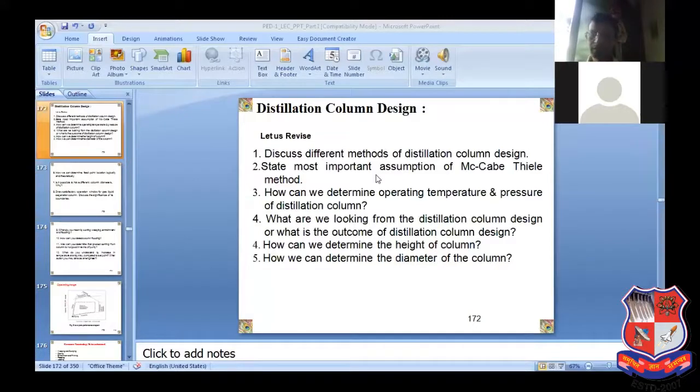If you remember, if you go through the assumptions given in the McCabe-Thiele method in a mass transfer operations book, then you can see that I can assume constant L1, L2, L3 only under one condition, because on each and every tray there is a transfer of molecules. Fine, mass transfer is taking place, concentration is changing, but still your molar flow rate, kilomole per hour, remains constant.